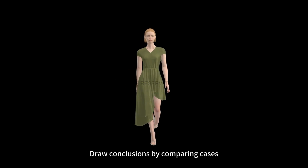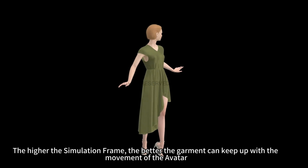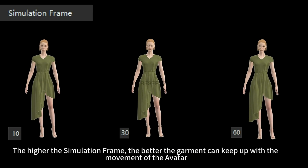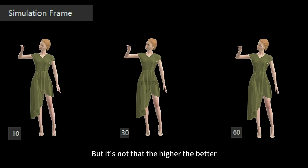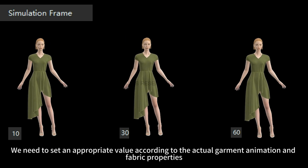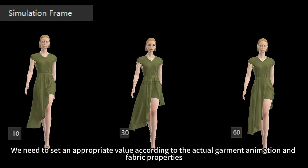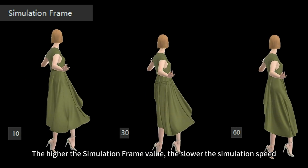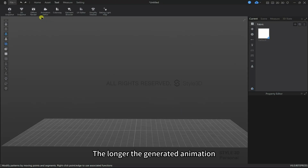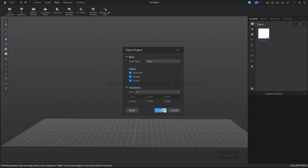Draw conclusions by comparing cases. The higher the simulation frame, the better the garment can keep up with the movement of the avatar. But it's not that the higher the better. We need to set an appropriate value according to the actual garment animation and fabric properties. The higher the simulation frame value, the slower the simulation speed, the longer the generated animation. Okay, let's move to the second case.